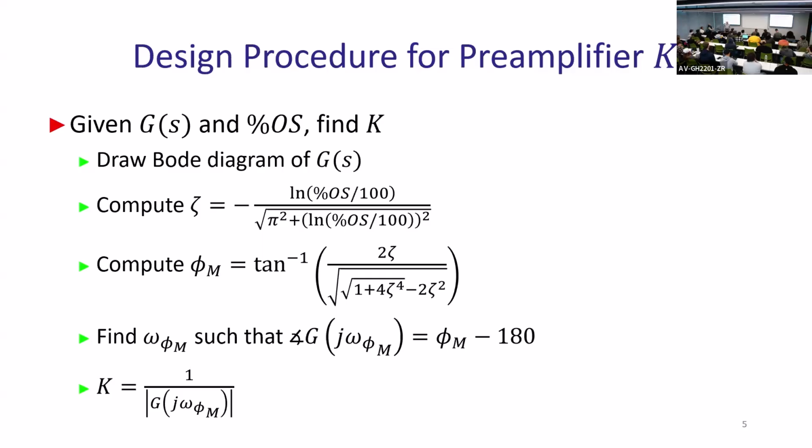Pay attention that log of 1 divided by x is minus log of x, which means it will be minus the value of the Bode diagram at that point. That's it. So your gain will be practically the inverse of your value of gain at that particular frequency in dB, or 1 divided by K, which is 1 divided by gain, which is the same thing. Any questions on the procedure before we get to the example?